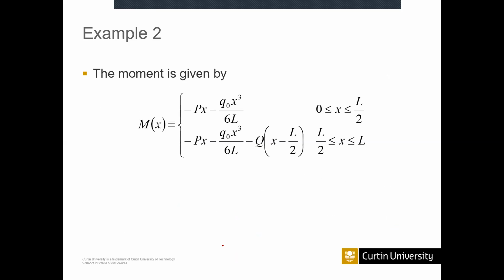Yeah. So you can see the bending moment. Take a general point when you calculate the bending moment. Don't take the upper boundary or lower boundary, something like that. So don't calculate the midpoint bending moment at point C, because then you will again eliminate Q. We should have Q as well to find the deflection. You can see here Q is available. Now what you need to do is find the first derivative with respect to Q.